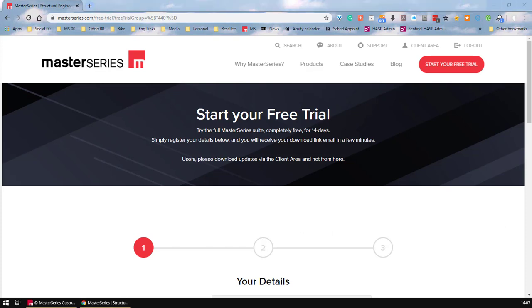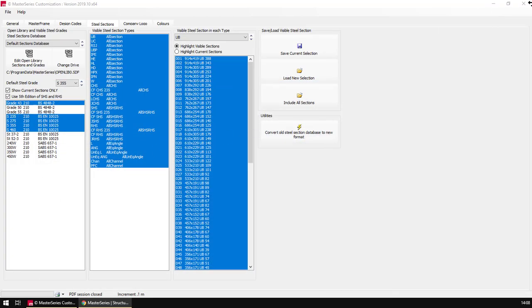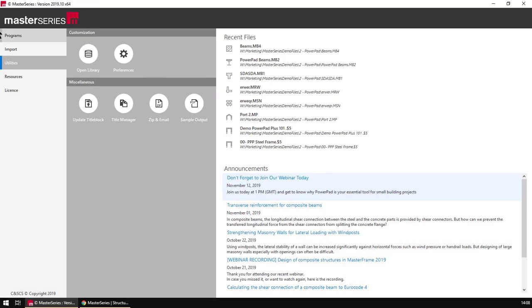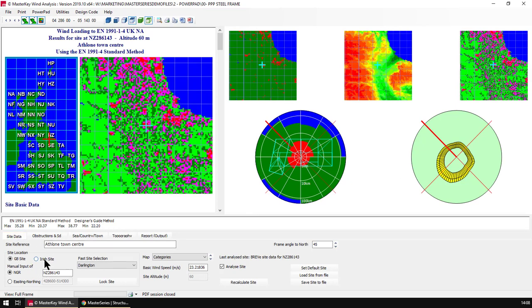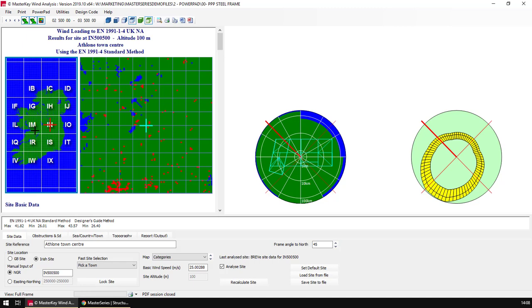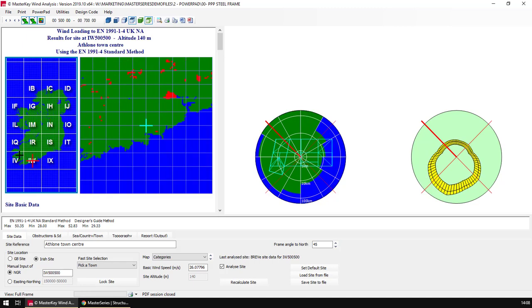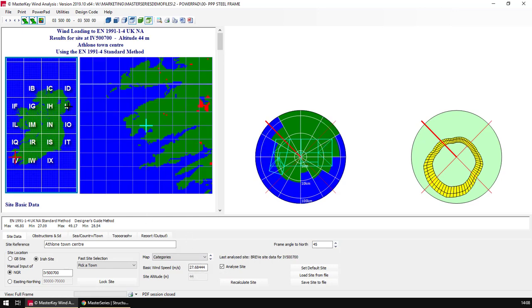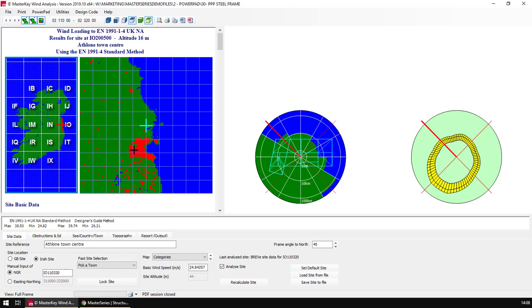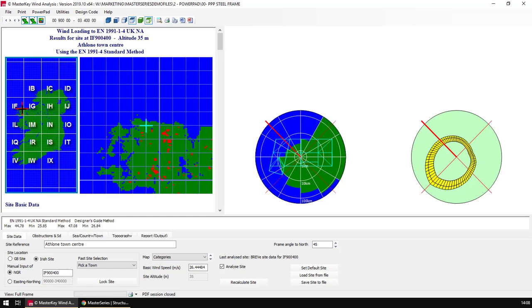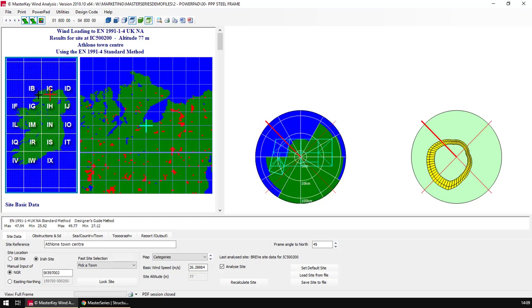Can you do wind design for any part of Ireland? Absolutely, Stephen, that's not a problem. Just coming back, say yes, go into my little frame that I was playing with earlier, into wind analysis. Very straightforward. Loads, wind, site data. Okay, if I change from UK to Ireland, I get an Ireland map, so I can choose a location and see what the basic wind speeds are. Quite significant. 27. Dublin is, I think, down in that little nook. Yep, Dublin's there, and you'll see it's only 24, whereas up out here you're up to 26, and if you go into the mountains in Donegal, you also are quite high.